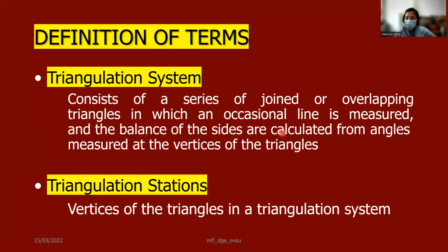But all of the angles are measured on the ground. The angles are determined on the ground, and the lines are computed after the angles are corrected.